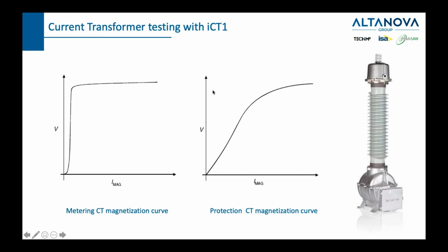And at the same time, let's say the knee point is here, this will be 10, 20, 30, 50, something like that. Not more than 100, probably. Maybe in some cases there will be, because there are many types of CTs. While in this case, if we have the knee point here, this will be 100 or 300 or 400 or 1 kilovolt or 2 kilovolt.